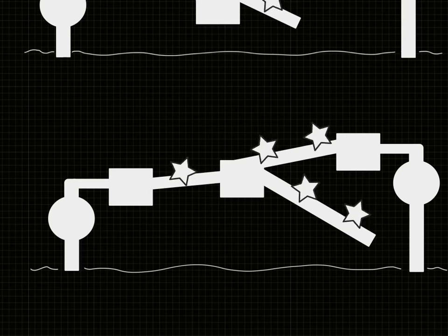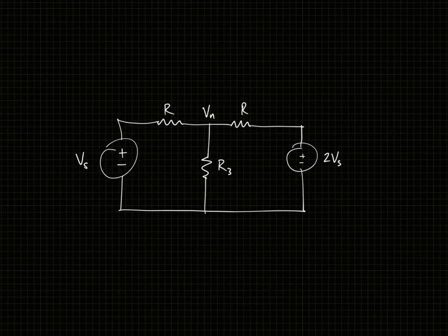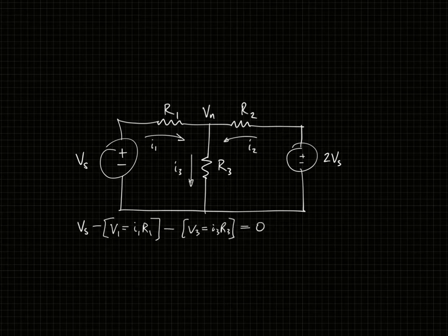But as I just showed, we don't know which way the currents are going yet until we solve the circuit. So let's take a look at this schematic and label the currents arbitrarily for now, and then solve every parameter in the circuit in order to find out which directions the currents are actually going. So doing a voltage loop starting here, which I'm just calling my common location. I haven't labeled it. I could call any location my common, but it makes the most sense to do this one, because it has the most branches coming into it, and it's also the easiest to relate to the sources.